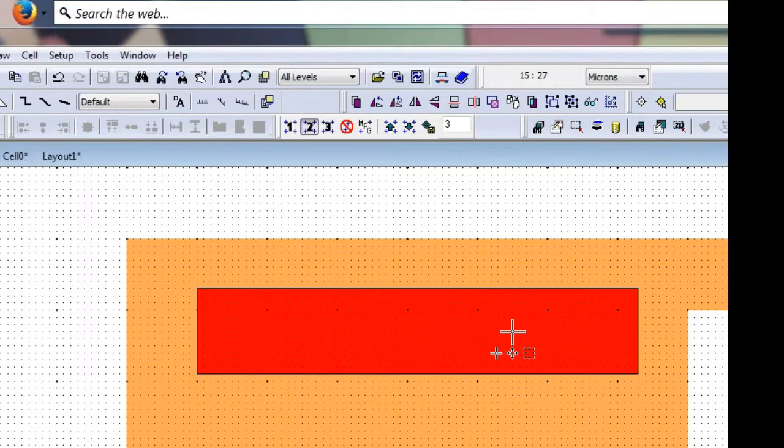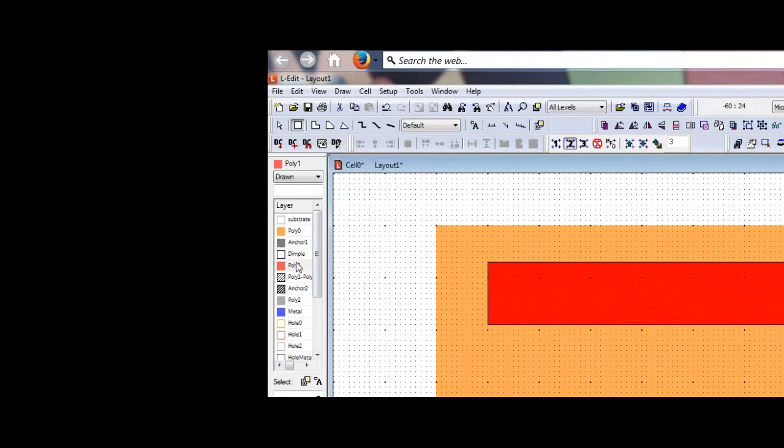And then when I go to remove the sacrificial oxide in between, it would float away because it's not grounded to anything. So I got to stick an anchor in there. So I'm still drawing boxes, which is fine, and I can go in and I can draw an anchor. And this is anchor 1. There is an anchor 2 as well, okay? But we won't talk about that on this assignment. We'll talk about anchor 2 later on the other assignment.